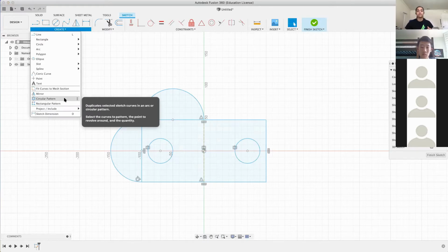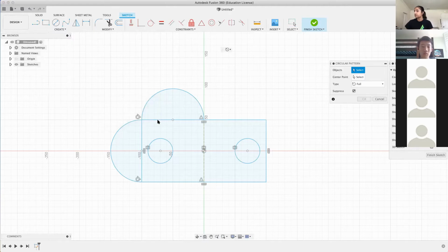Well, if you guys have ever looked at a standard FTC motor, you'll see that on the top of the motor, where you can actually screw the motor into something to mount it, it is a circular pattern of screws. And there are two ways you could create a circular pattern of holes in this case, so that you can mount something like a motor to your part. One of them is you manually measure everything, where you measure the distance between all the circles, you make sure you get all the angles correct if it's, you know, like 6 holes in a circle. The other way is you actually use a circular pattern. And so I'll show it to you real quick.